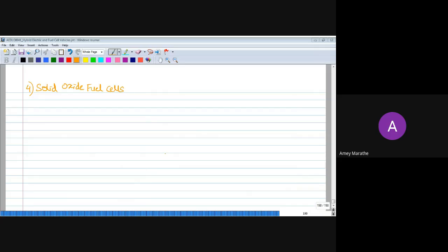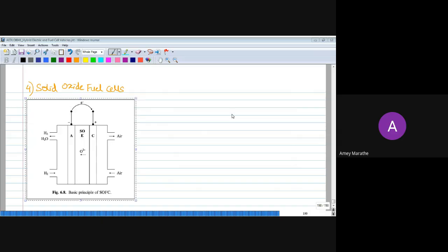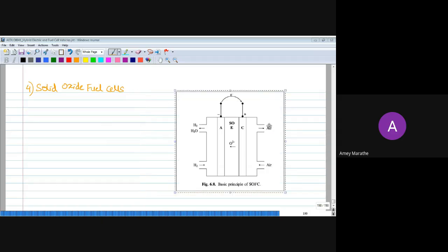Once this idea is clear, the working of a fuel cell becomes very simple. There is going to be an anode and a cathode. We supply fuel, which is hydrogen, to the anode, and oxidant, which is air, to the cathode. What is going to change is the electrolyte. And as I said, the name of the fuel cell is based on the type of electrolyte used.